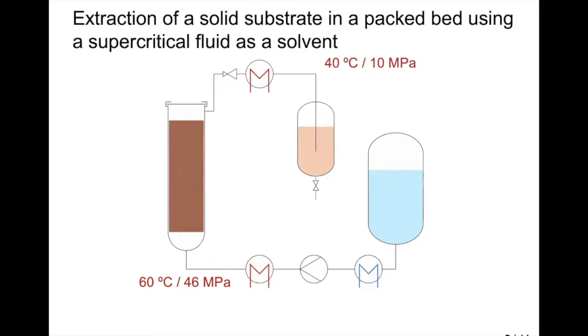To avoid solute precipitation in the tubing because of the abrupt temperature decrease, the so-called Joule-Thomson effect, CO2 is heated downstream from the expansion valve. Gaseous CO2 is condensed and stored again in the working tank. Makeup CO2 is supplied to the solvent cycle to replace CO2 losses when reconditioning the extraction vessel or removing the oil from the separation vessel.